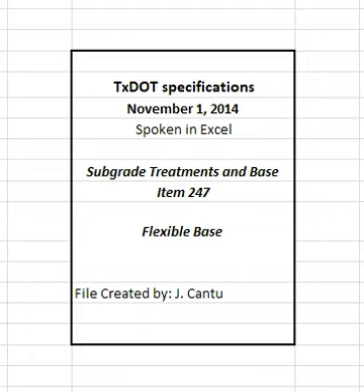4.3 Compaction. Compact using density control unless otherwise shown on the plans. Multiple lifts are permitted when shown on the plans or approved. Bring each layer to the moisture content directed. When necessary, sprinkle the material in accordance with Item 204, sprinkling.